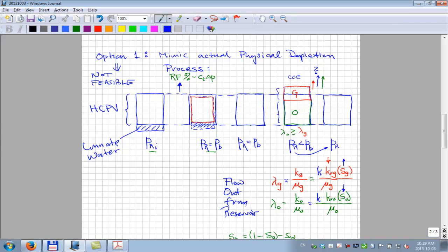In the worst case, you put your well at the top of the oil reservoir, right? The very top of the structure. What's going to happen then? You've got high permeability, you get gas coming out of solution. Where does the gas go? To the well. What do you produce from the well? Gas. What do you not produce from the well? Oil. Recovery not very good. Okay? And then you got everything in between. But we could take out some oil, we could take out all the oil, take out some of the gas, we could take out all of the gas.